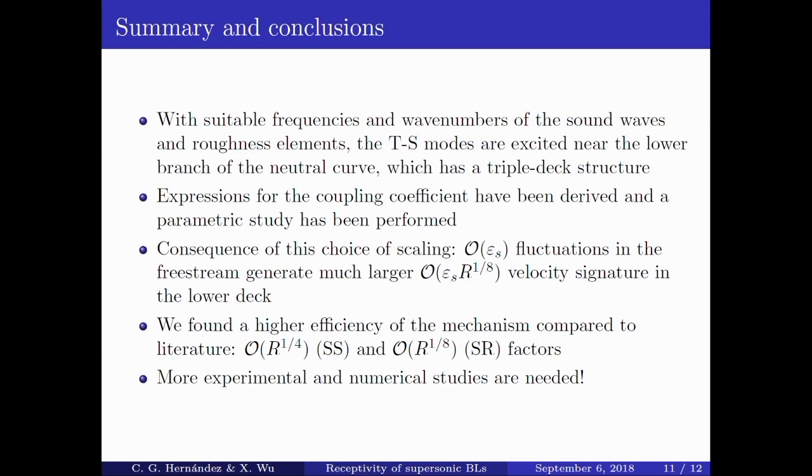In particular, for the sound case, we compare the strength of the receptivity found here with the one of Wu 1999. And it's about a factor of Reynolds to the 1/4 larger. And for the sound roughness case, which, as I said, has already been studied in the literature, the factor is Reynolds to the 1/8 larger as well.